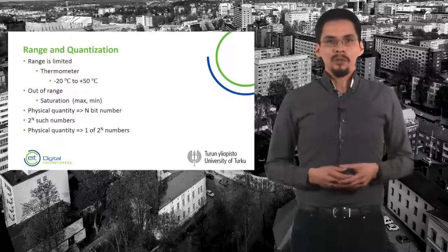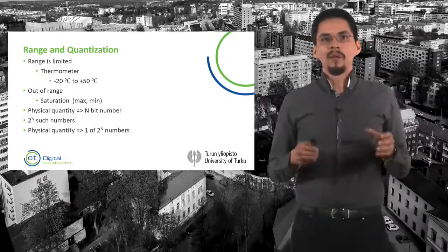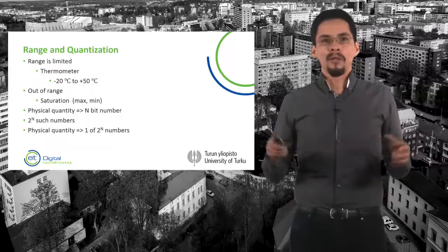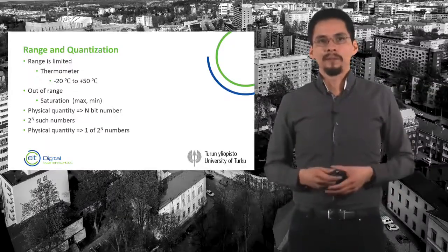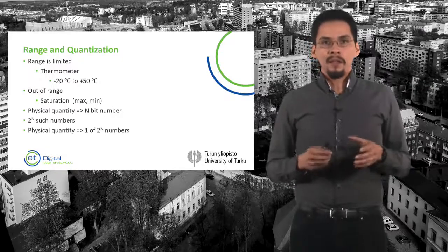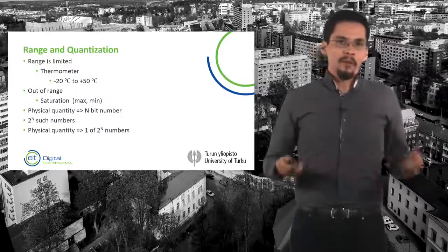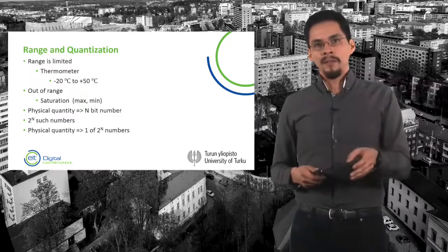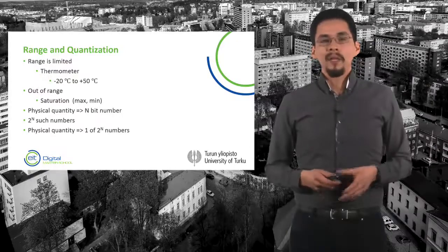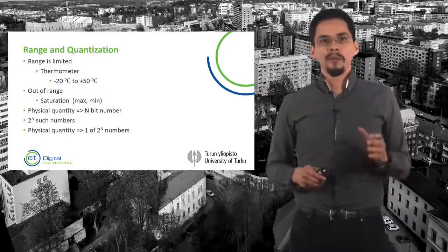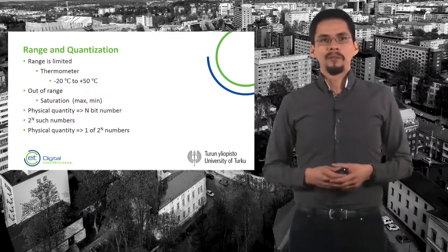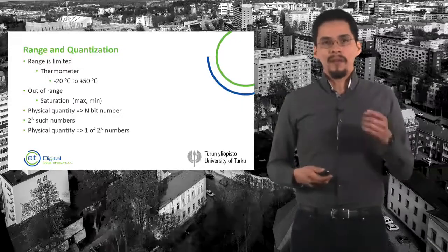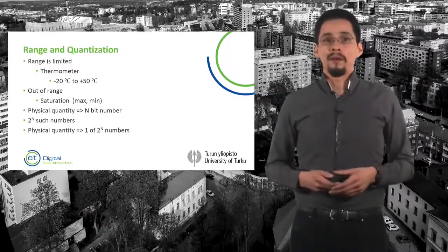For some applications, it may be not enough to have just 256 values to represent the whole range of changes of some quantity. In this case, the number of bits, or in other words, the resolution, should be increased to 9, 10 bits or more. Sometimes the only way to increase the resolution is to change the hardware. At this point, you can think of the cases where the quantization error will be the largest.